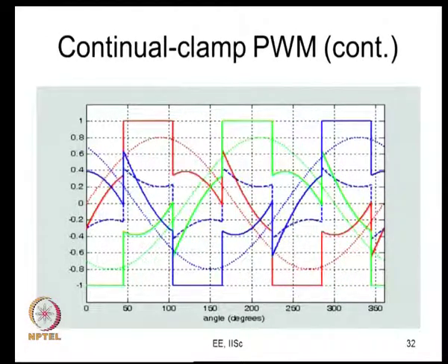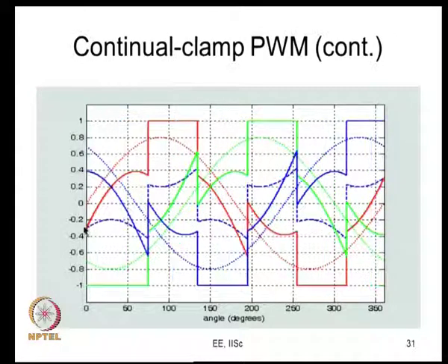Alright. So, depending on the power factor, you can vary your PWM clamping location. So, as long as the load is lagging or leading and the angle is not more than 30 degrees, it is possible for you to clamp the phase exactly when its current is around its 0 crossing, for 60 degree duration around its 0 crossing. So, for example, here if your current is having its peak here, you can clamp it around 30 degrees before and 30 degrees after the current peak.